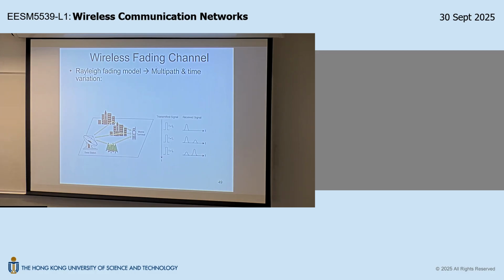Now in a wireless channel, in a radio communication, what is the reason you have this inverse square loss? Why will your receive power be reduced by 4 times if you double the distance separation? That has nothing to do with ohmic loss, right? So consider an isotropic transmitter, radiating power in all directions in deep space.